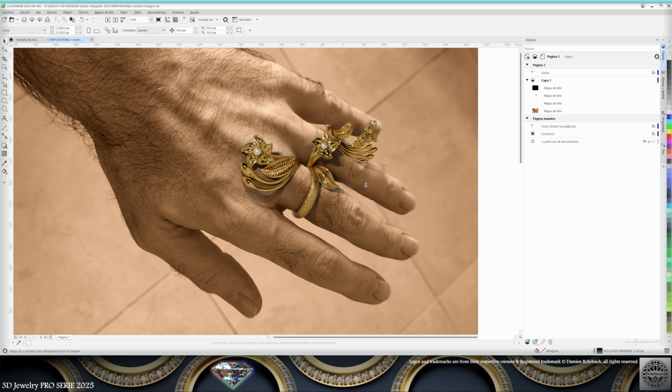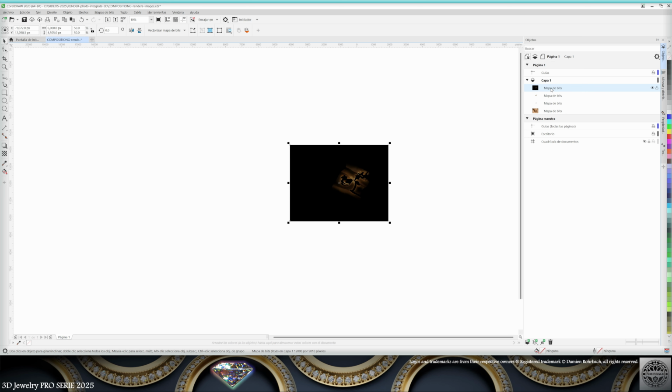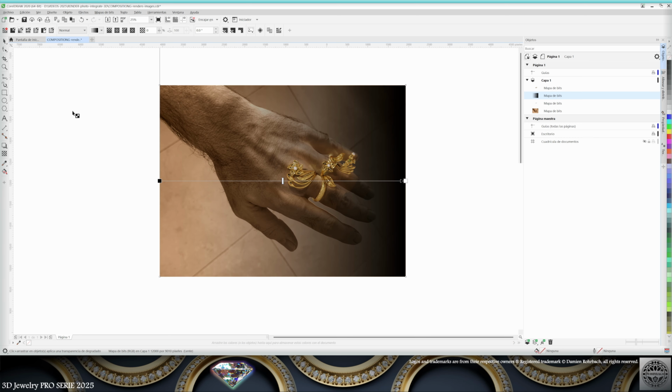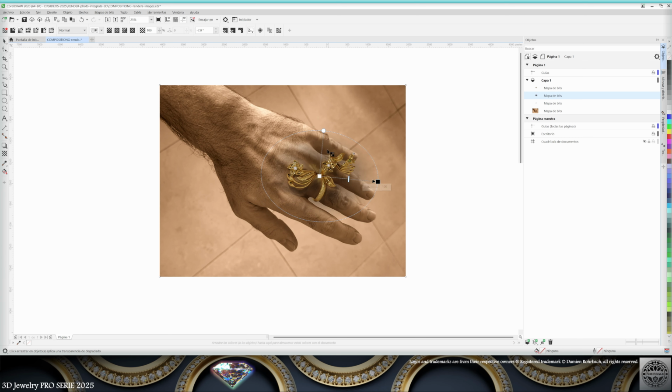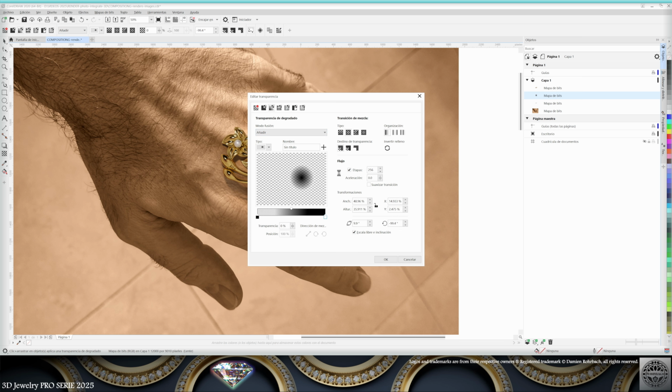Now let's bring the metallic bounces. So let's overlap and scale. Now this image needs to be under the ring render, but over the rest. Now here I need a gradient transparency to limit the range of this image and have a smooth transition. And I'm going to change the type of transparency to add. So obviously the light from this image is adding to the rest because the metallic bounces are bringing light. Now also I'm going to edit the strength of the transparency.